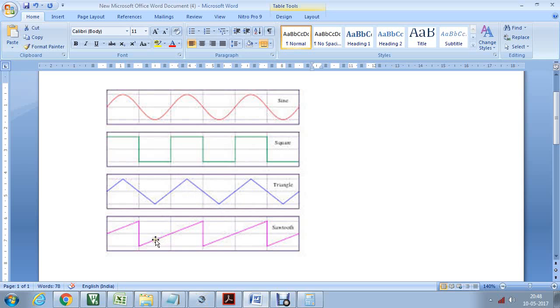But as far as a ramp signal is concerned, it has to go from a low value to a high value. Low is nothing but 0 volt to maximum voltage 3.3 volt, and after 3.3 volt it should suddenly decrease to 0 and it should start from here. So I have eliminated my second loop here, so it will start from here to there, and it will suddenly decrement and go. So the signal will be like a ramp signal, right?